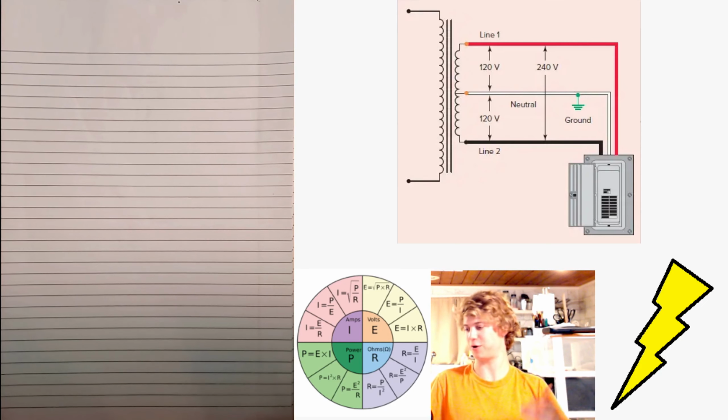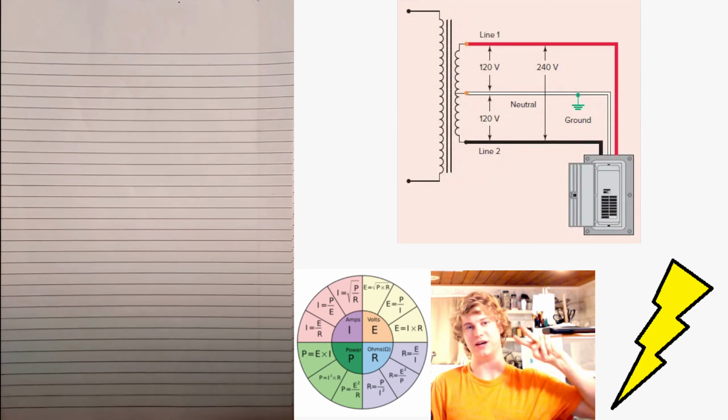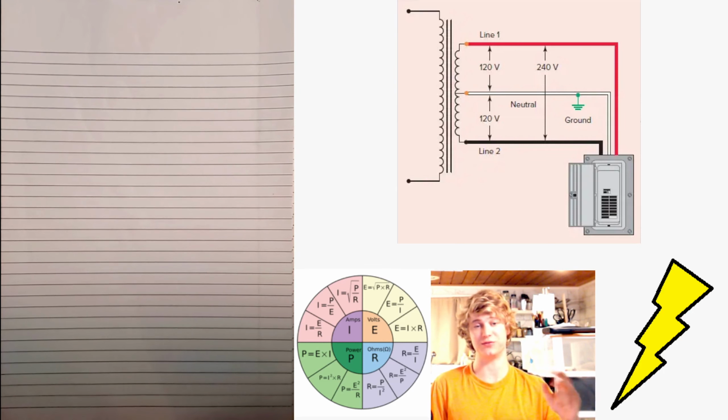Okay, so now back to the article. The electric service supplied to a residence normally consists of a single-phase voltage supply with a center tap transformer, as you can see in the picture above. So most people already know that most residential homes are run on single-phase power, which consists of two lines and a neutral. The lines are often called phase A and B, but how everything is wired and run, this is a single-phase system. Don't think this is a two-phase system.